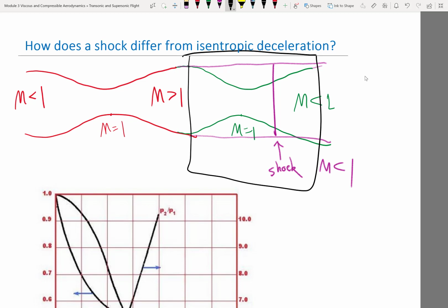So some energy is converted to heat, right? Some energy may be converted to sound, but it comes out of here. So the conservation of energy equation is actually not different, right? So if, for example, you assume that the density, pressure, temperature, velocity, Mach number, and everything downstream is the same between the green case and the purple case, then the outflux of energy should actually be the same.